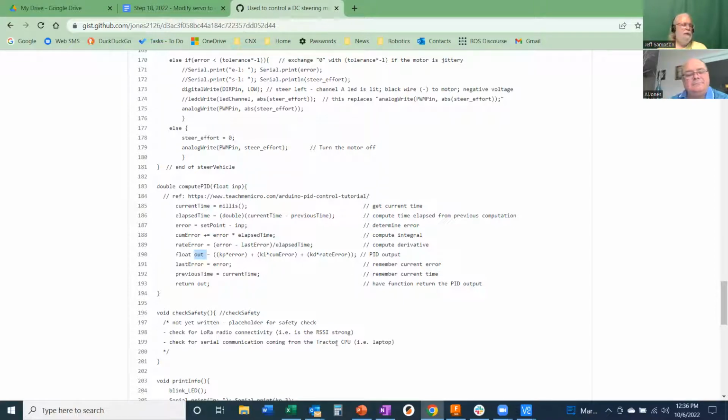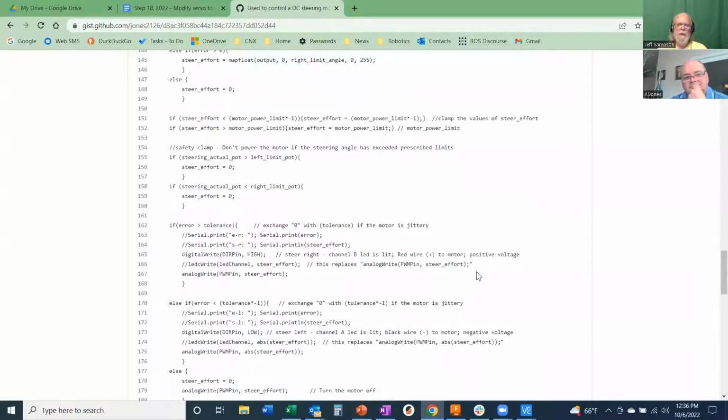And you might want to look at those other, you had several examples of somebody doing PID stuff, see what they're doing, because they're going to call the PID function and then do something with that. And I'm assuming if you look at those, they're going to just take that number. In your case, you want to limit it to plus minus 255, because that's what the PWM won't take anything more than that. And then down below, where you're saying if error is greater than 0, that should say if output is greater than 0. That tells you which direction you want to go. And then if you scroll to that thing where you're doing the PWM and the thing that said if error is greater than 0. Let's see what code you got in there.